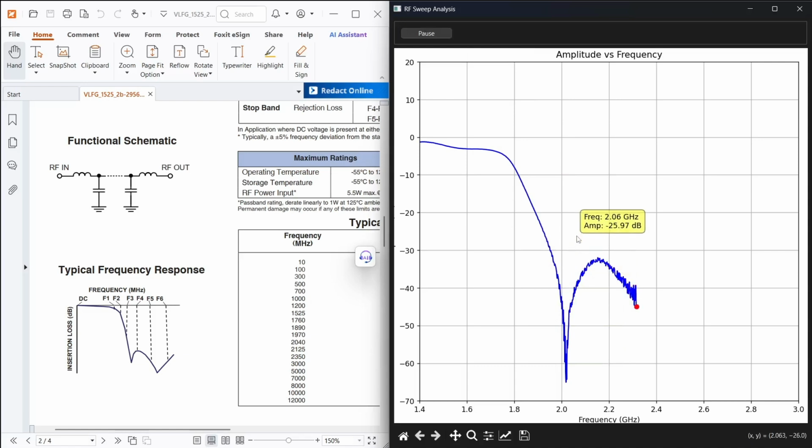So I resumed the sweeping here. These are just some basic functions built in here. You can see it comes back, comes down, goes back and comes down again. We see the same behavior happening as we continue. One thing to note here is that we are seeing some rippling. One of the reasons is that our attenuator is also supporting up to 3 gigahertz, and we are getting close to that. But for this case, because I don't want to fit the cable exactly to our ADALM Pluto without the attenuator, I just kept this as is. But hopefully in the future we get a better attenuator.